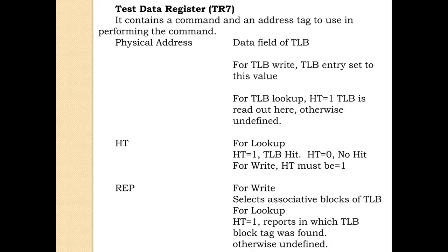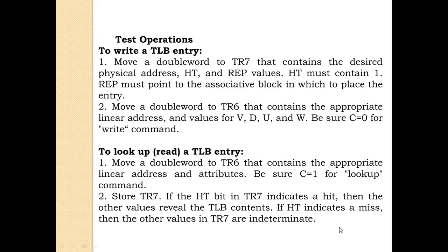The REP bit is there. For a write, it selects associative blocks of the TLB for the lookups. ST equal to 1 represents a TLB hit, otherwise undefined. Test operations: to write a TLB entry, move a double word to TR7 that contains the desired physical addresses.